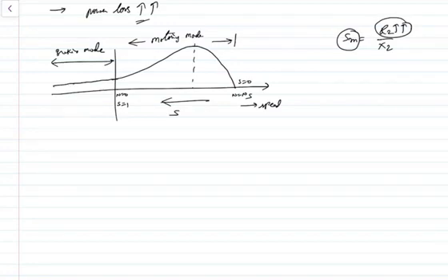Let us assume if you are increasing the value of the resistance, how the curve will shift. So I am just representing with some different color. Even I can make it like this. The slip corresponding to maximum torque will be here at this point. In that case, the curve will shift like this. Even I can shift it further. I can make that the slip corresponding to maximum torque will be at the time of starting. In that case, your curve will shift like this.